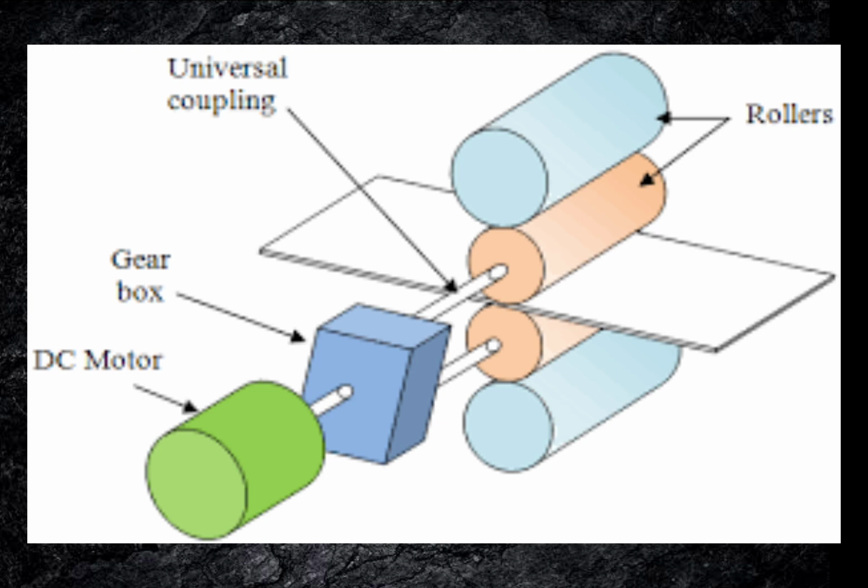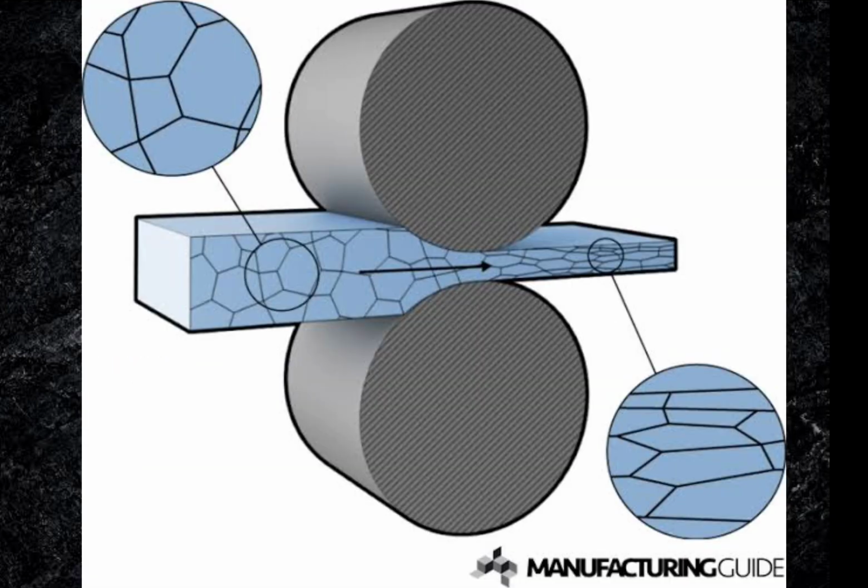In terms of physical characteristics, cold-rolled steel is typically harder and stronger than standard hot-rolled steel. While hot-rolled steel is heated then cooled, cold-rolled steel is cooled at room temperature and followed by annealing or tempers rolling. This additional process allows a wider range of finishes and closer dimensional tolerances.